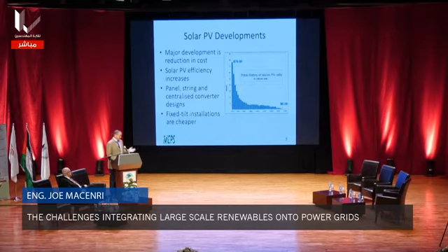And then there is a third major technology, which is called thin film technology. I've never actually worked with that myself, but that's a cheaper technology again, but its efficiency is lower. It's lower probably by about 6–7% than polysilicon. So where you have a lot of area and land is not at a premium, the thin film may be the better way to go. But in general, the cost per kilowatt has dropped dramatically, certainly in the last 10 years.